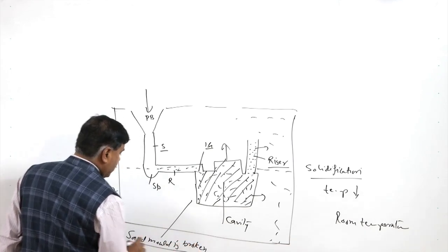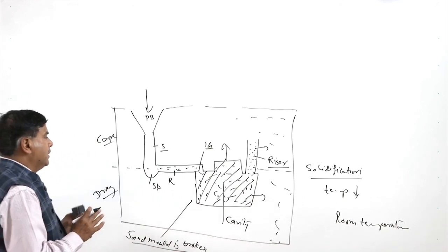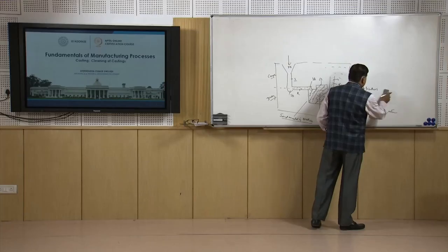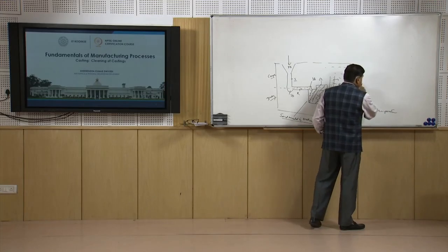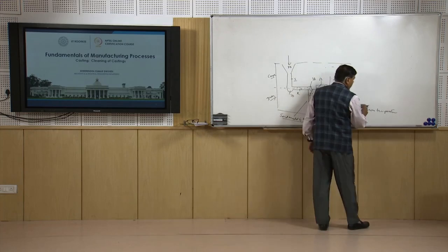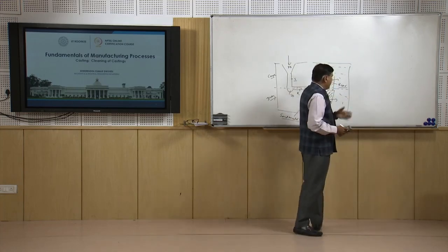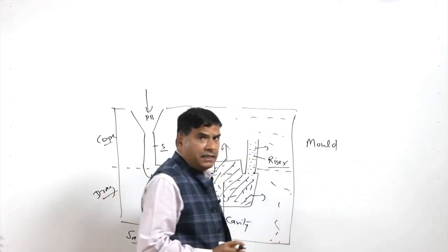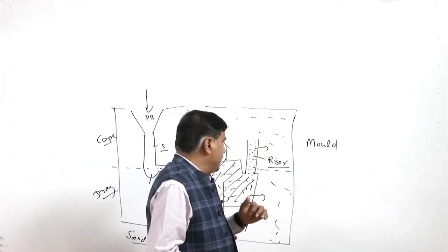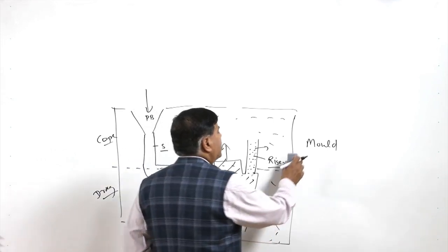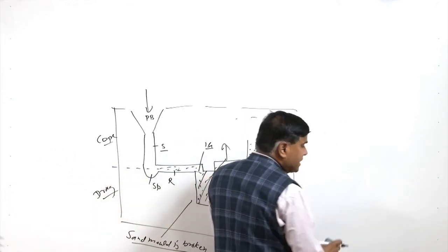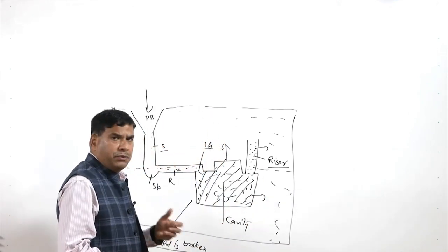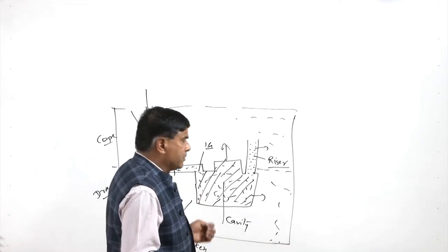At which stage, meaning at which temperature, should the sand mold be broken so that the casting remains intact and has the desired characteristics and quality? Because if the mold is broken at a high temperature, it can lead to the breaking of some of the parts which are thin in section, and it can lead to warping or, due to the residual stresses, it can lead to cracking.